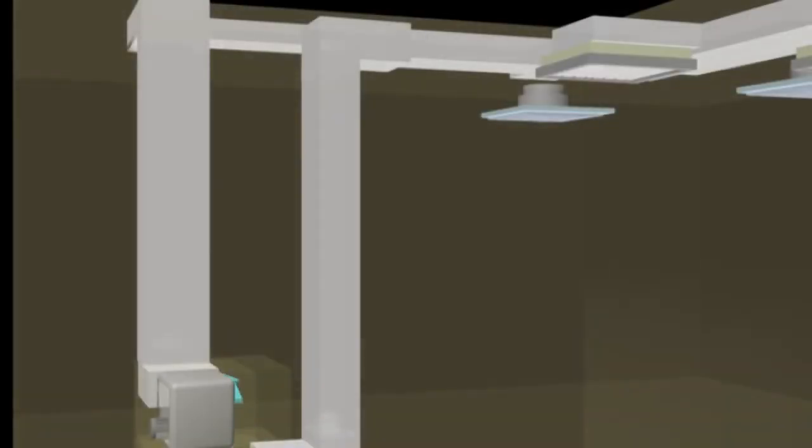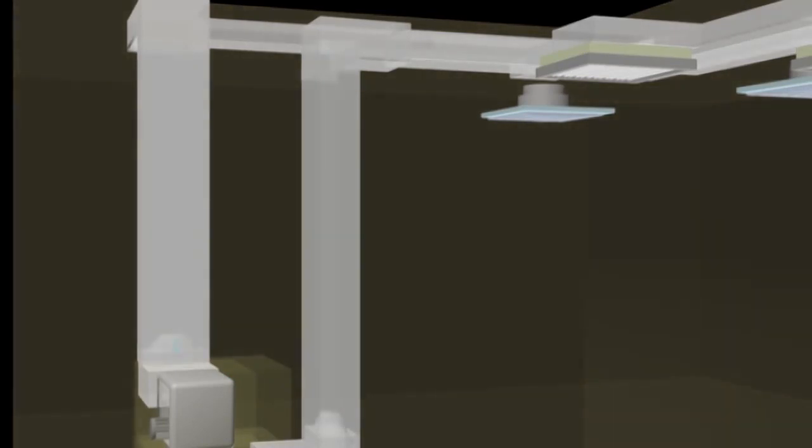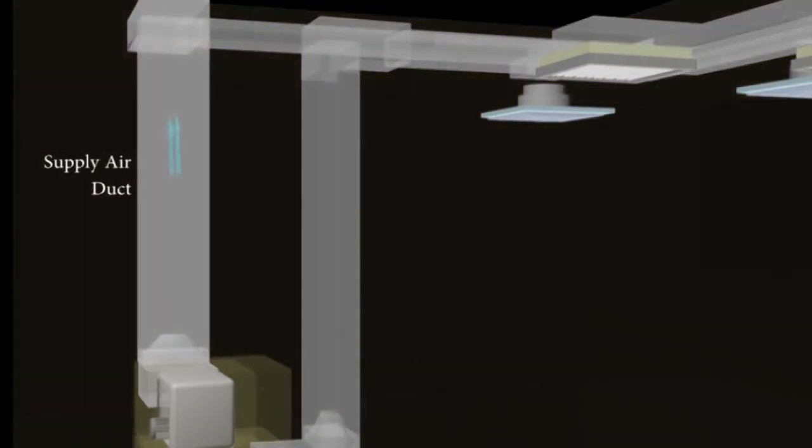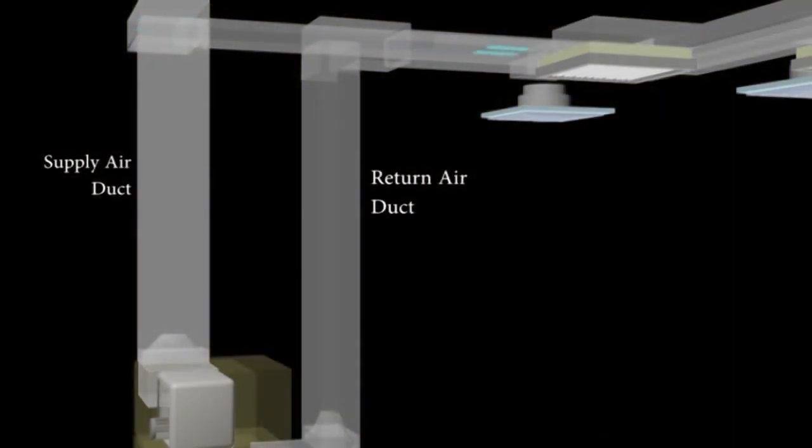The channel through which air flows is called ducting. There are two types of air duct which are supply air duct and return air duct. These air ducts are coated with insulating material consisting of fiberglass wrapping with aluminium foil. It reduces heat transfer from the environment to the air duct.